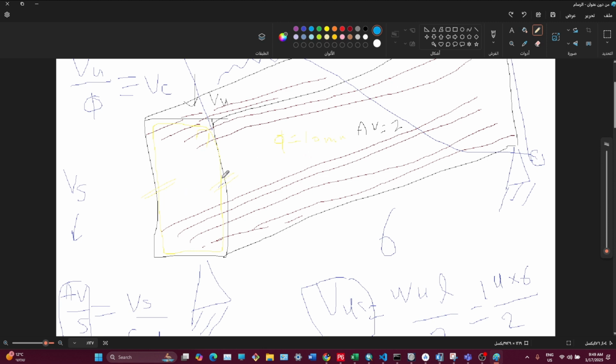Then, if the diameter of this stirrup is 10 millimeter, we have 10 millimeters diameter, squared, times pi over 4, and by 2 is equal to the AV. Okay. Now the AV over a spacing. Now I have two options to assume the diameter of the stirrup, then I can compute the spacing. This is the AV.